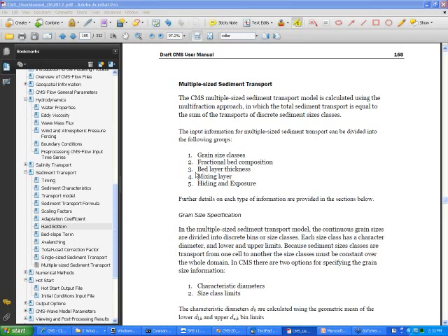There's more things. I talked a little bit about the bed slope coefficient, and that term is like a smoothing term, it's like a diffusion term. You can increase that bed slope coefficient, and that will smooth your bathymetry more and reduce instabilities. Usually, we don't have that problem. We don't have very often instability problems with sediment transport.